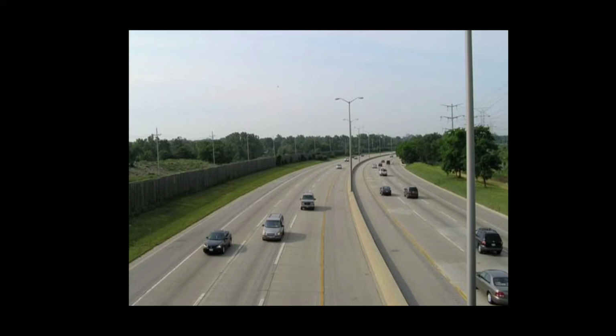The first advantage is that CC pavements of major roads are generally designed and constructed for a 30-year period, and therefore the service life could be 30 years and more than 30 years also. The routine and periodic maintenance cost is very low, as maintenance of joints only is required. The life cycle cost of CC pavements is much lower than that of flexible pavements.